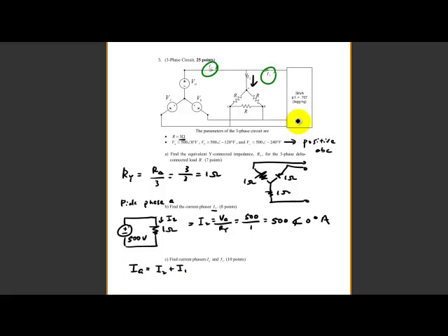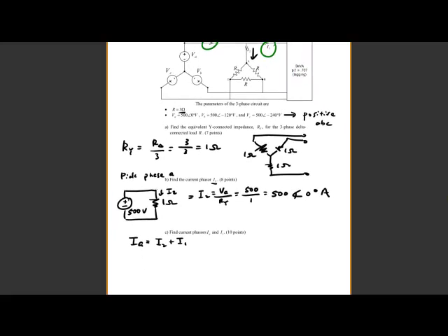As I said before, you have to consistently use the same information here. So 3 kVA with a power factor of 0.707 lagging. This is actually a three-phase box because you can see 1, 2, 3, and the total power is given. So you will have to use this information divided by 3, because you are treating it as a per phase analysis.